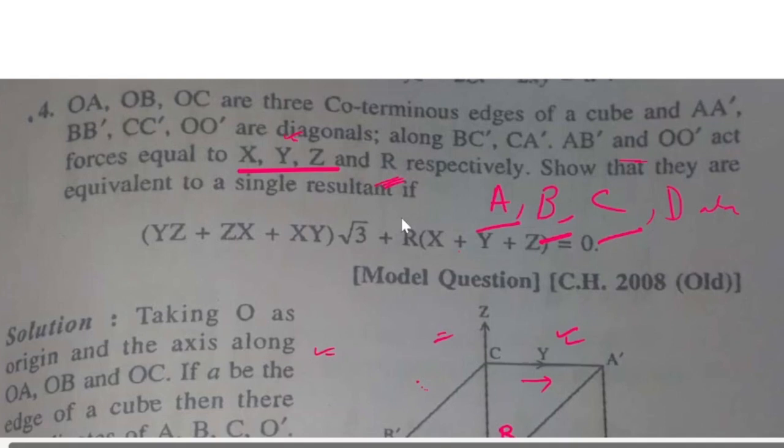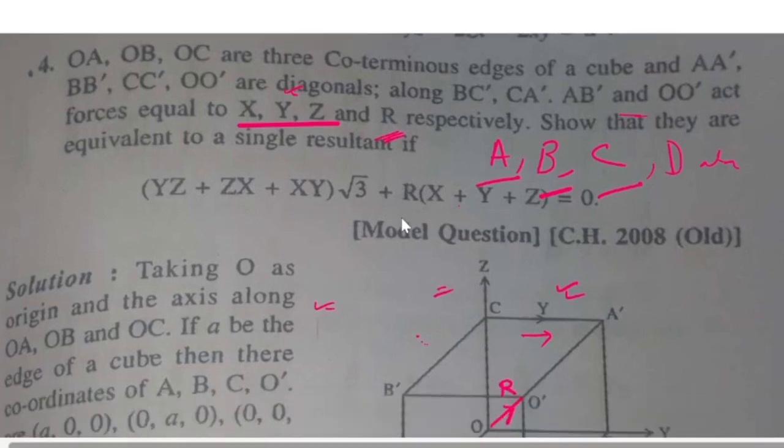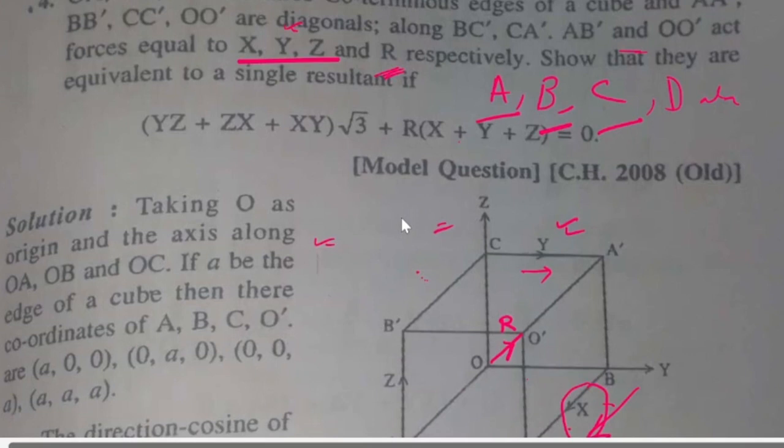But what we are choosing here, as we already discussed in the lecture, whenever we go through the theory of force in three dimensions, we said we have to fix a base point, we have to fix a reference system with respect to which we will measure everything. So for here, as per the problem given, once we take this O as the origin, and once we draw a cube having X, Y, Z as three edges, then it will be easier for us to deal with the problem. But that is not mandatory.